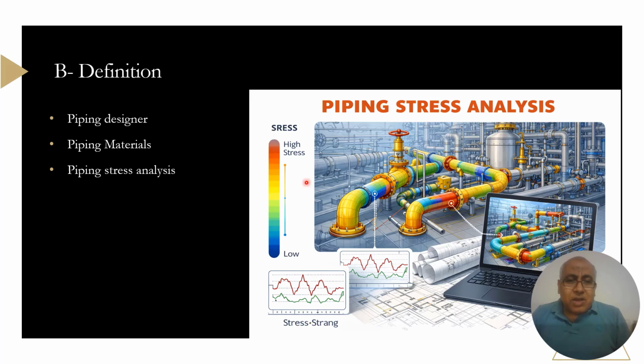Then we go through the pipe stress analysis, which works like what we do, but we use software here, Caesar and AutoPipe and so on. It is the same for the piping and the pipeline. We define the stresses. What about the supports themselves in the case of piping? What about the piping itself, the strain of the piping? We define the stresses on it after applying the load, like a steel structure working in a structural program. We work here with Caesar or AutoPipe, but the concept is the same as for structures.